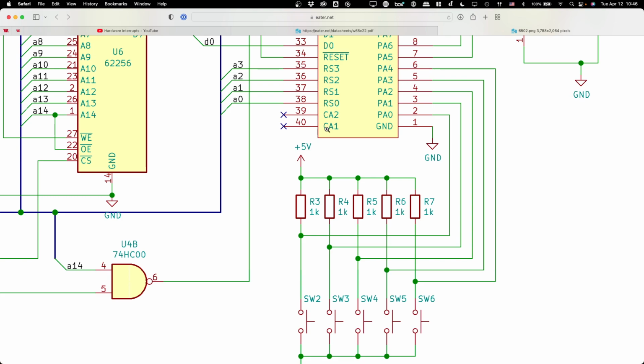If we had wired the buttons using pull down resistors instead of pull up resistors, then we would use OR gates, because we would be going from 0 for not pressed to 1 for pressed. But we're sort of backwards, and like you learned in discrete math, what's the logical opposite of OR? An AND of the NOTs is the NOT of the OR.